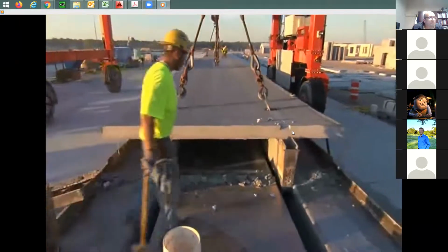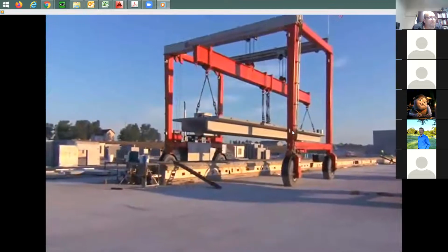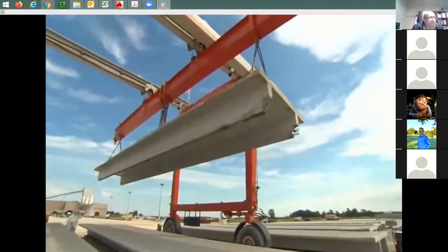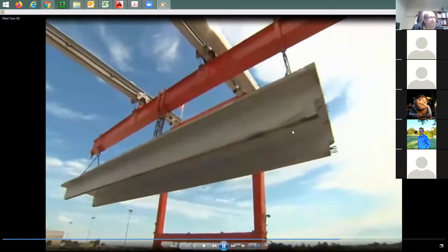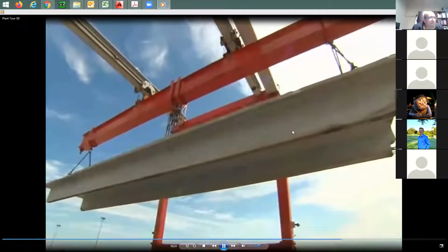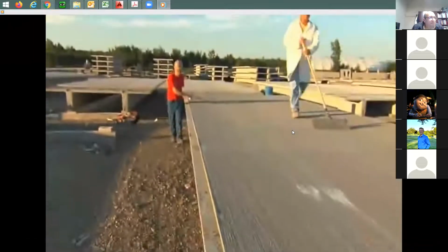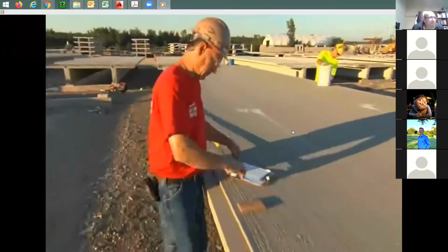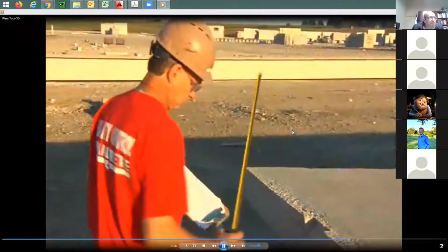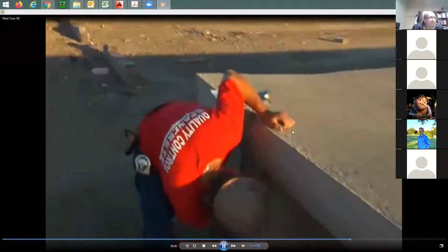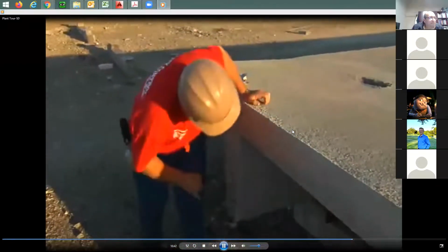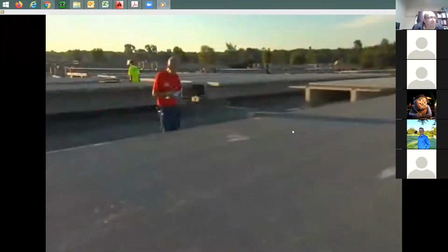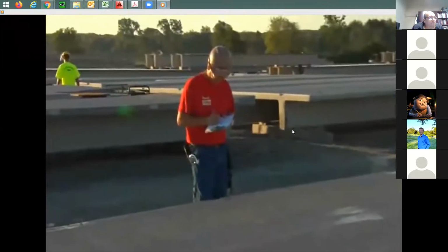Cables are attached to the lifting devices, and each piece is removed and transported to a detailing area for any minor cosmetic touch-ups. Also at this time, the QC department does a post-pour QC check on each piece that is brought to the detailing area. When I first get back there, I go and check the length of the piece and verify that within a tolerance of probably 1/4 inch or so. Check the width, we check the vectors, we check the electrical blockouts. I do a visual for any type of discoloration in the stems underneath the piece, any type of surface cracks, bug holes, just do a complete visual. Any defects are noted so that repairs can be done before shipping the tee.